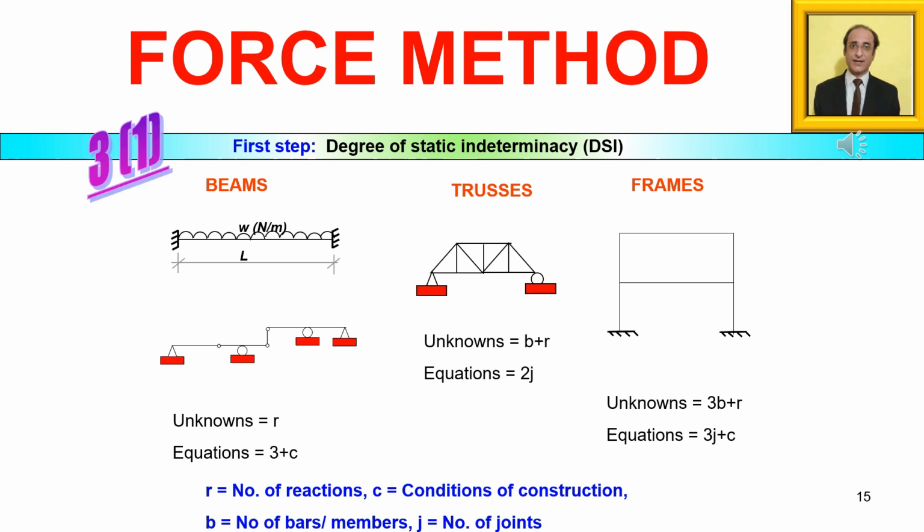So the first structure, where we have a beam under UDL with fixed end supports at both the ends. If you work out the degree of static indeterminacy using the method learned, you will come out with the number 3. However, now by observation of the conditions of symmetry and taking into account the fact that in beams there is no axial force, we can further bring it down.